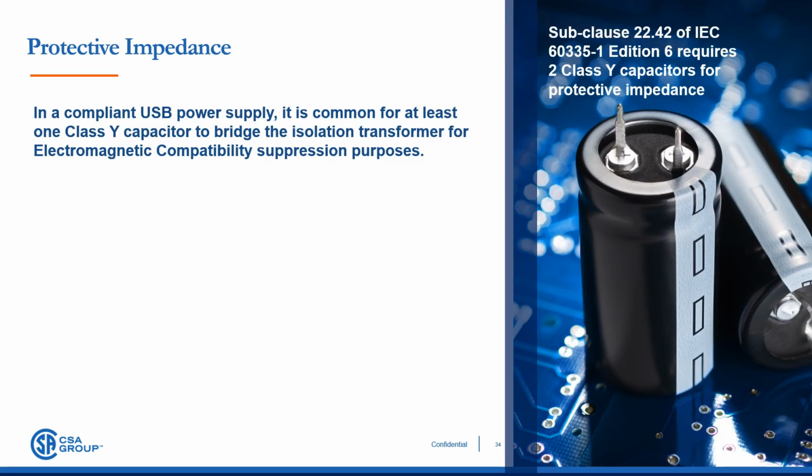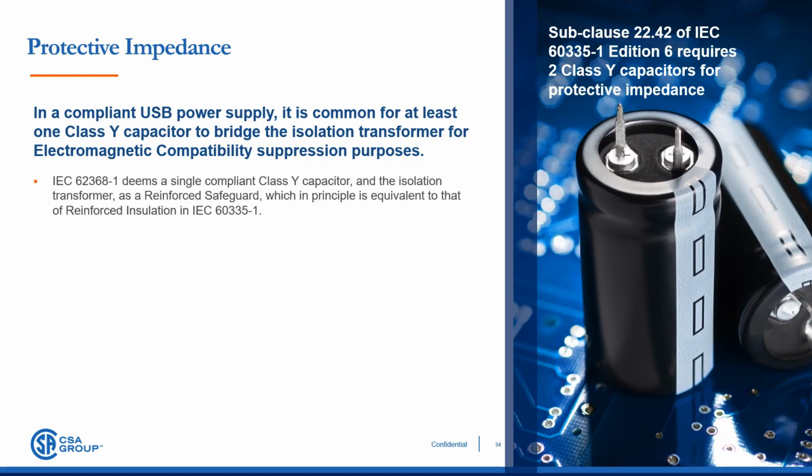A single compliant Class Y capacitor and the isolation transformer itself is equivalent to reinforced safeguards in IEC 62368-1. The principle of reinforced safeguards is directly equivalent to that of reinforced insulation in IEC 60335-1.